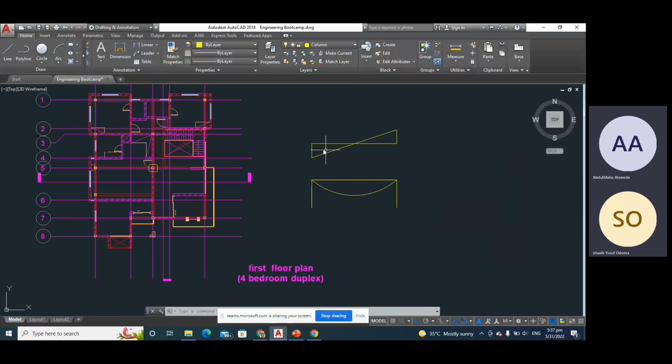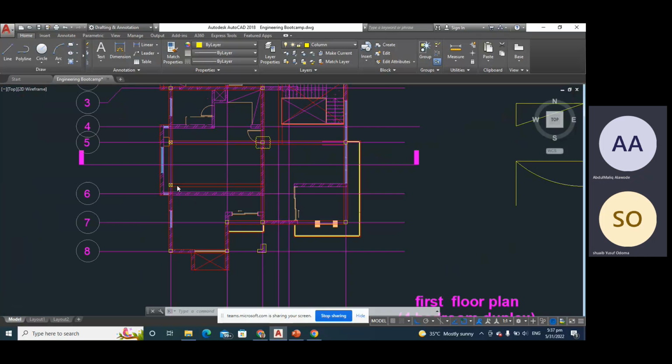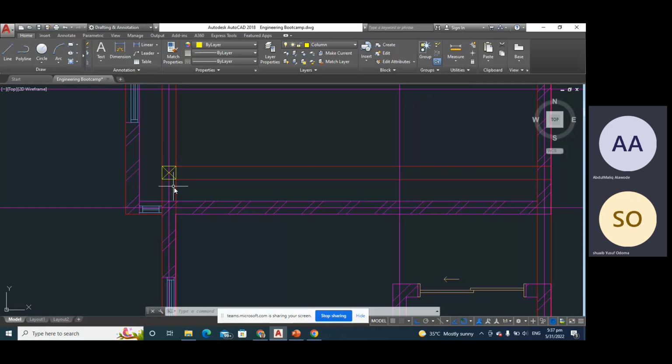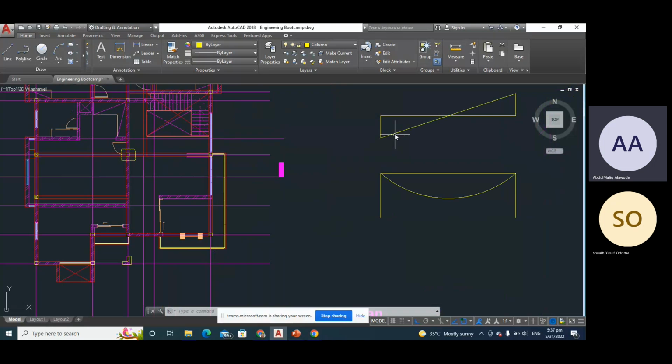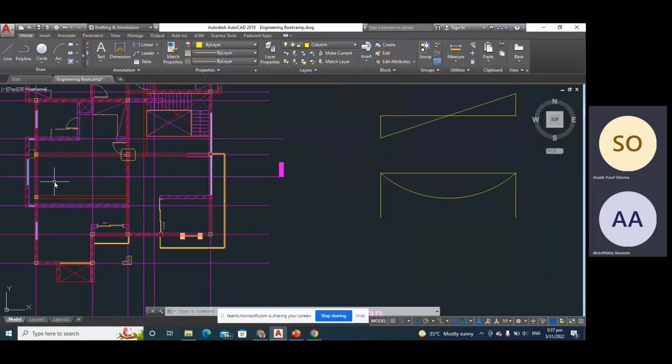The axial load is the value of the shear force that you have here. The shear force here is what is going to translate to the axial force that you are going to use when you are doing your manual analysis. Although, since we are using software, the software is going to do everything for us. So the value of the shear force in this diagram is going to translate to your axial load at this junction. Are you following me?